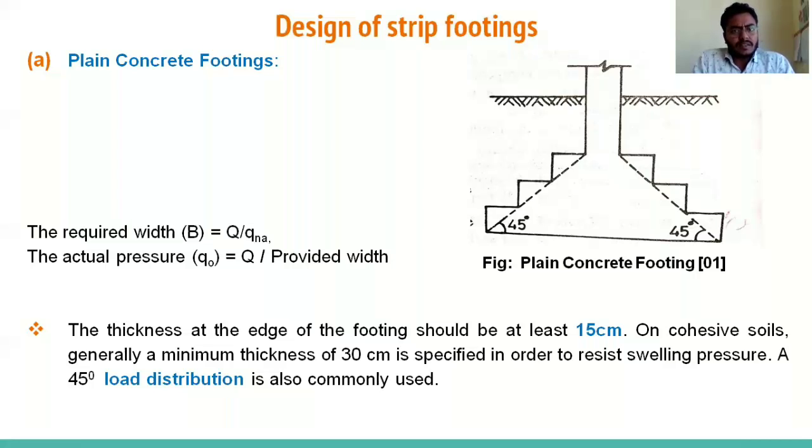When we are going to select the depth of the footing, we have to take care of the black cotton soil, because that soil is very different in nature. It can swell and it can shrink easily. Suppose you get water, it can swell, or when it dries, it will shrink. So it will affect the footing, right? So that is very important. Selecting the depth of footing to take care of the soil is very important. What kind of soil is there?